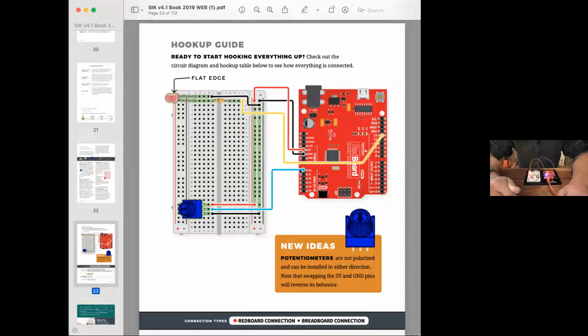And so now let's look at this just a little bit. I talked a little bit about a digital signal, the on off, or ones and zeros, or in our case here, it's 5 volts and 0 volts. Any of these ones here on the Arduino board along the right side of it are digital inputs and outputs.